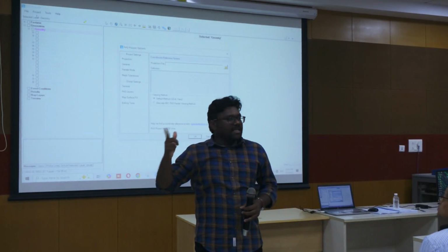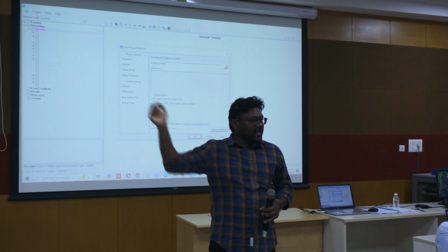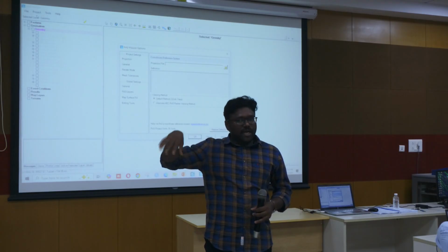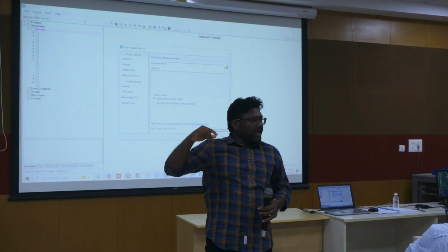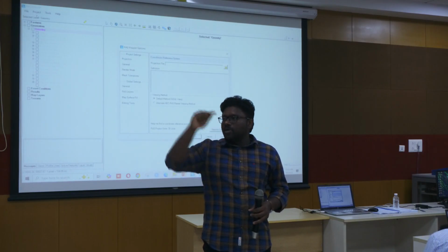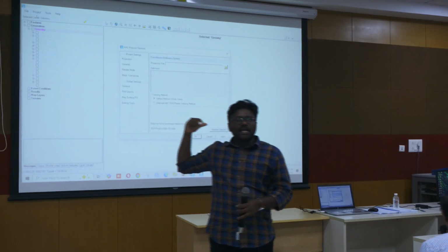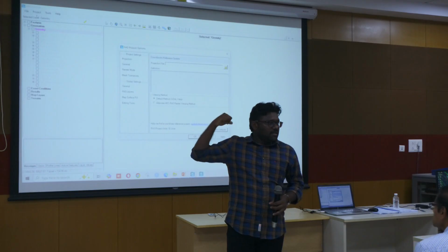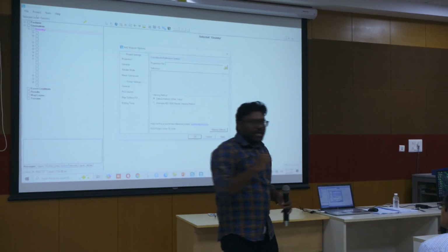Whatever HEC-RAS file we developed, I told you we can export the shapefiles from that HEC-RAS. In the same way, I exported. If we export any layer which is already projected, the exported layer has the same projection. So we are just taking the projection from that shapefile. Okay?